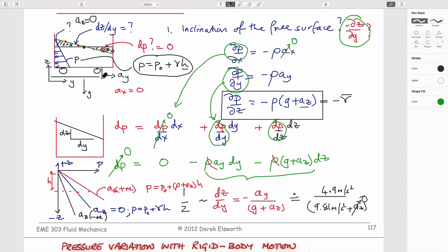So in other words, this is a truck trundling on rollers, then the acceleration vertically is 0. So if the acceleration is 0, this pressure distribution, even though it's piled up at the back of the truck, has to be just the same as if we're going down in a swimming pool that wasn't moving.